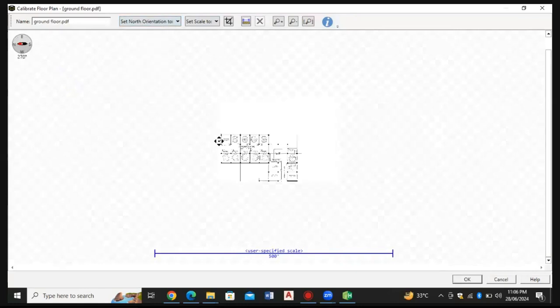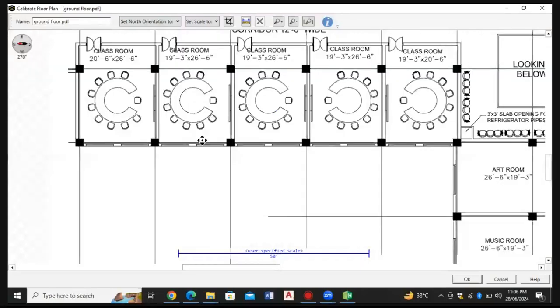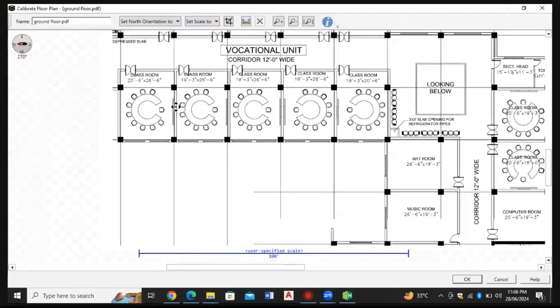So what we see here is that we have a new advancement in HAP 6.2. Like in HAP 5.1, I had to tell HAP all the exposed walls and their area and dimensions, like whether they are exposed to north, south, east, or west, and I had to tell about window area.